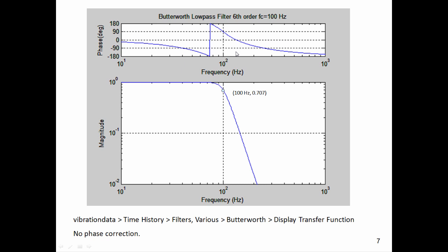Well, it turns out if we try and construct that filter, we get numerical instability, and that's just a fancy way of saying that our filtered signal would just blow up. We get some crazy high values. So for practical purposes, we have to accept this limitation, and the consequence is we're going to filter out some of the energy close to 100 Hertz, or I should say leading up to 100 Hertz.